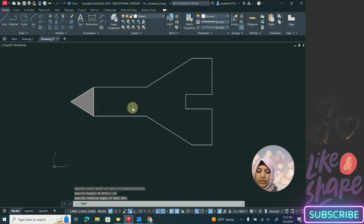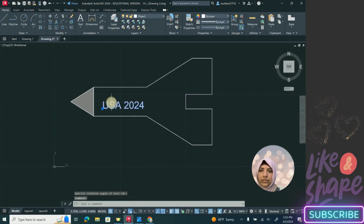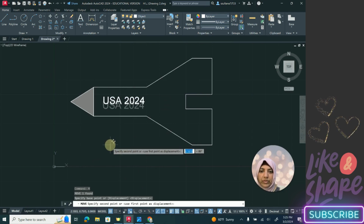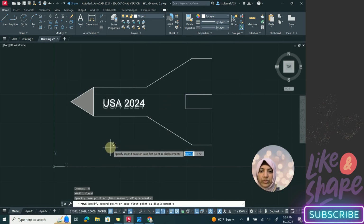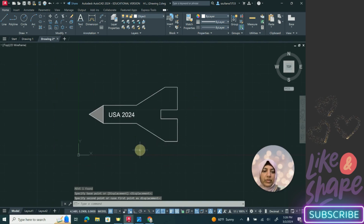And then start typing USA 2024, and then click outside of the text box, and let's move it using the move command. You can type M for move and click anywhere on the screen, and then move your cursor and move it to the center. So that completes your drawing.